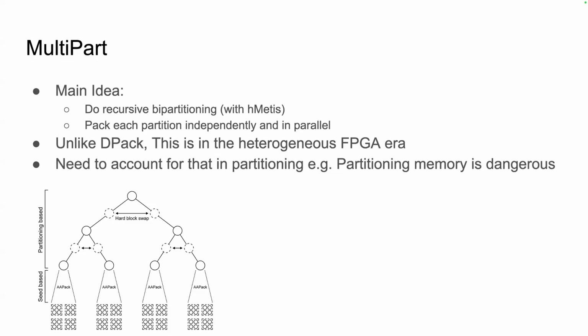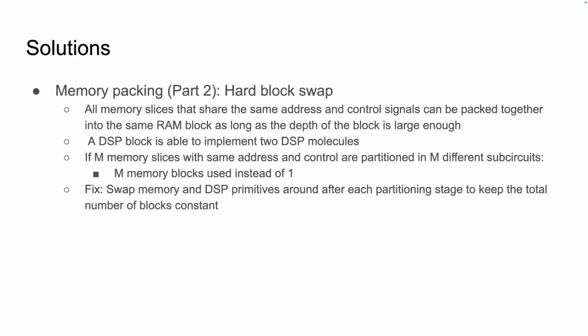Oh, and Vaughn, I did want to confirm something. You were talking about how the Stratix 4 architecture captures models of DSPs, like two DSPs per... Looking at the architecture, the DSP logical block has two half DSPs, and I think that's what they're referring to. But within a half DSP, you can have four MAC multipliers, and that I think is controlled by synthesis. Divided into two groups of four, basically. Yeah, that's what I think is going on as well. Yeah, that makes sense.